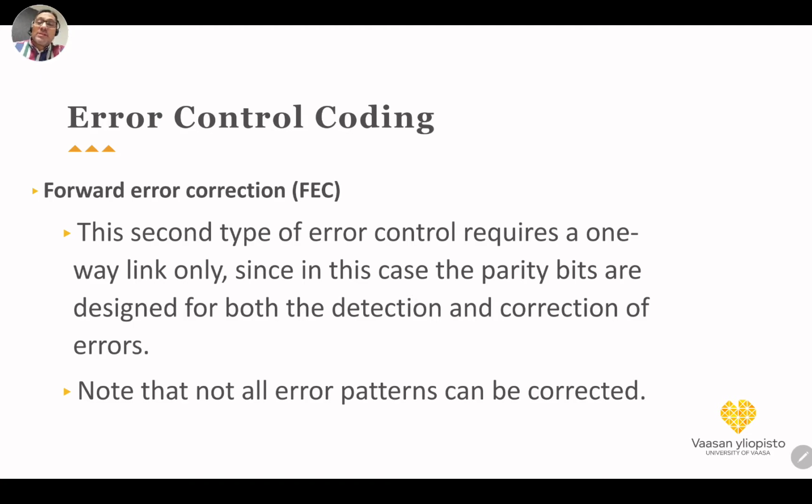Of course, we have hybrid systems, as we will see. They are widely used, especially in 5G and 4G. Hybrid ARQ is an ARQ system, but it also uses some FEC, like low capability forward error correction when we have a small error, or at least we can distribute it over more than one packet. So when you receive a packet in error, you can ask for retransmission, and when they retransmit it again, using forward error correction distributed over more than one packet, it can be used for error detection and correction at the receiver. So we can use a hybrid ARQ system.